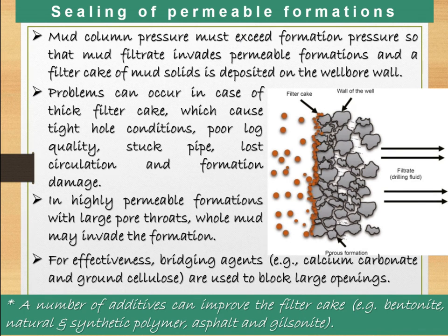This is called filter cake or mud cake, which can act as a wall and further minimize formation fluid entering the borehole. So the mud column pressure must exceed formation pressure so that mud filtrate invades permeable formations up to a certain level, and a filter cake of mud solids is deposited on the wellbore wall.